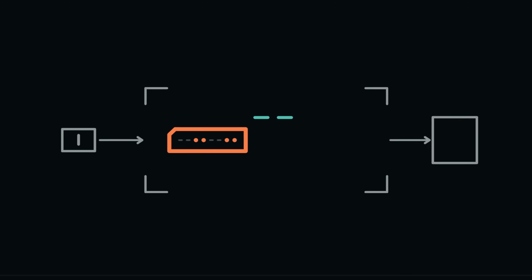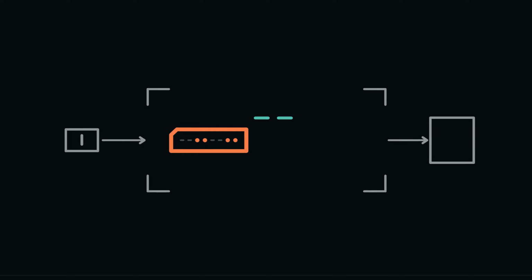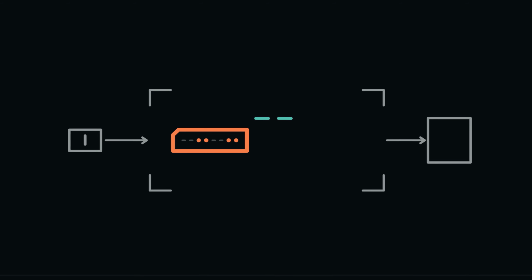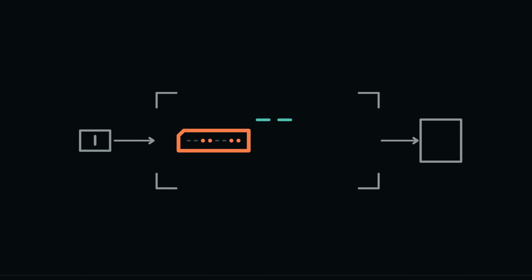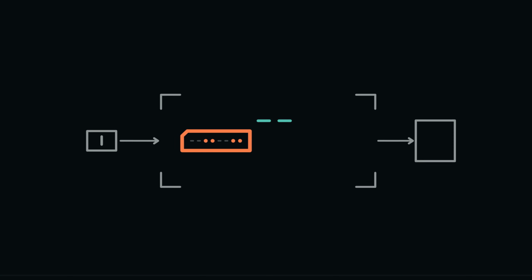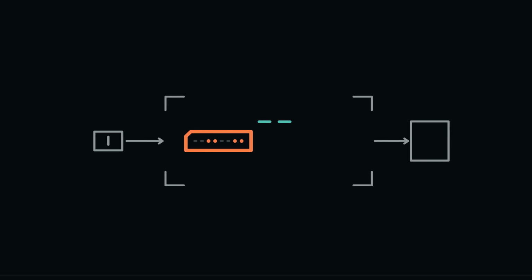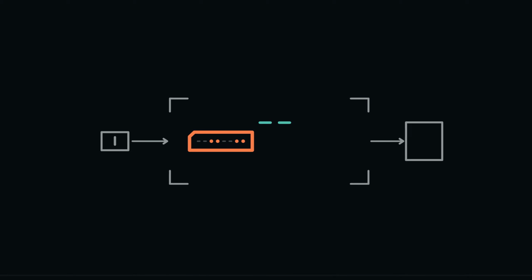2 settled bit values wait on separate routes, A above and B below. The next part of the machine has only 1 input. We do not want to combine the candidates, and we do not want either one to be changed. We need a 3rd bit, called select, to decide which candidate is connected to the output relation. When select is 0, output A. When select is 1, output B. That exact need comes before the symbol that will solve it.